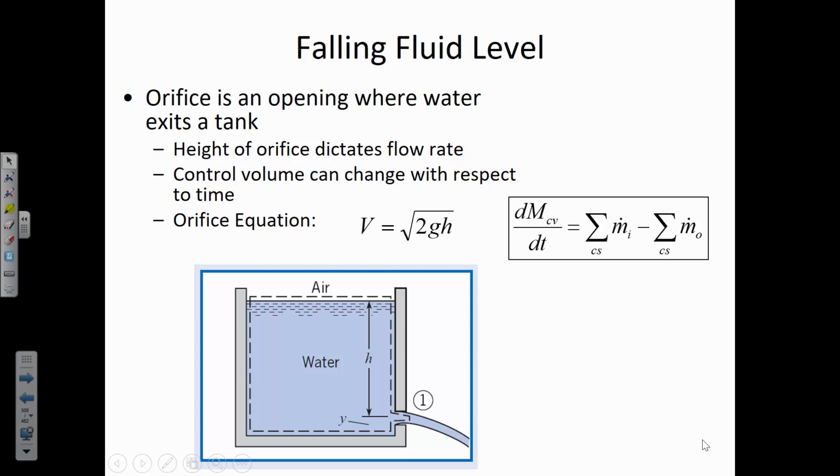The main thing we're going to do is cancel out this pressure head term so that H, which is the difference in elevation, is just equal to V2 squared divided by 2g. If we want to solve for the velocity, that's where the square root of 2gh comes from. It's just Bernoulli's equation applied between those two points, at the surface of the reservoir and just after the opening of the jet.